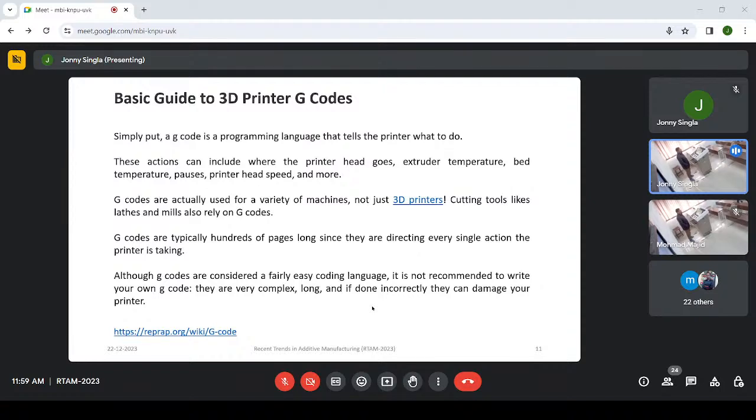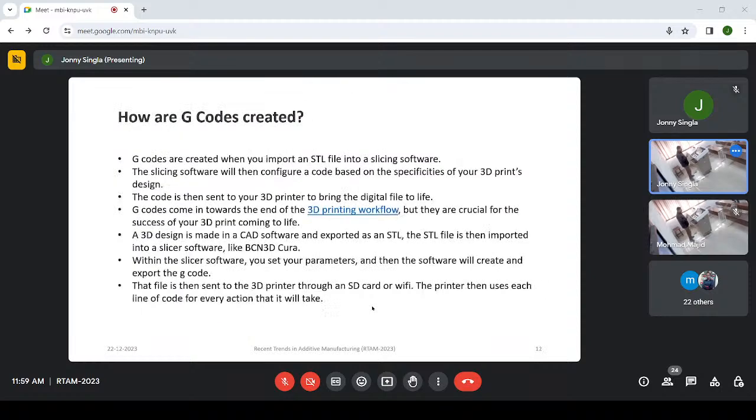Mostly, you might have heard about some codes like G00, G01. These are standard codes, and all manufacturers of CNC machines or 3D printing machines use these codes for that particular task, for travel only. It's not that some machine uses G00 for rapid travel and some other machine uses G100 for rapid travel. So there are some standard codes. We should follow that, and we should not generate our own codes. It will make things difficult for the users.